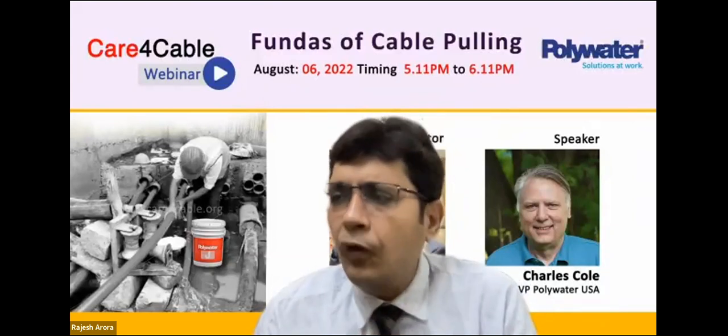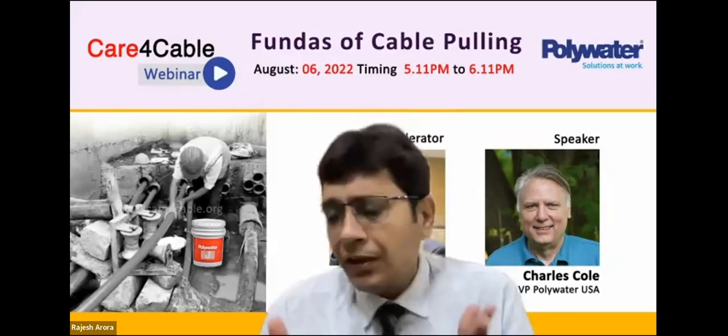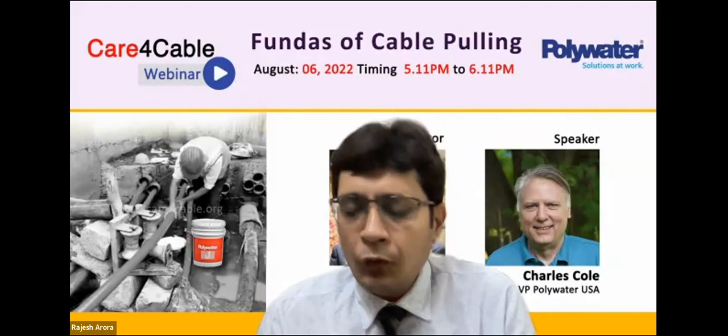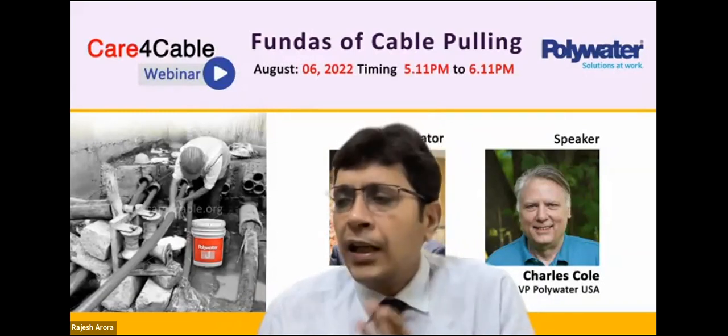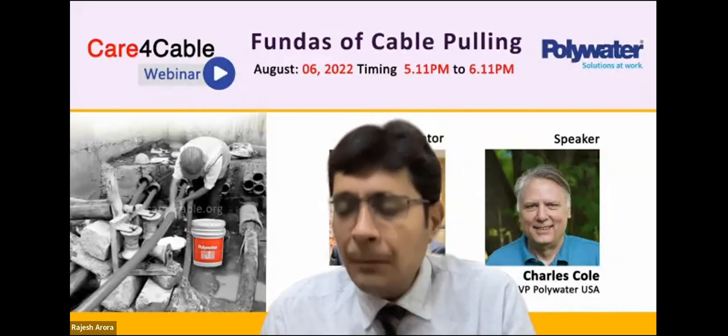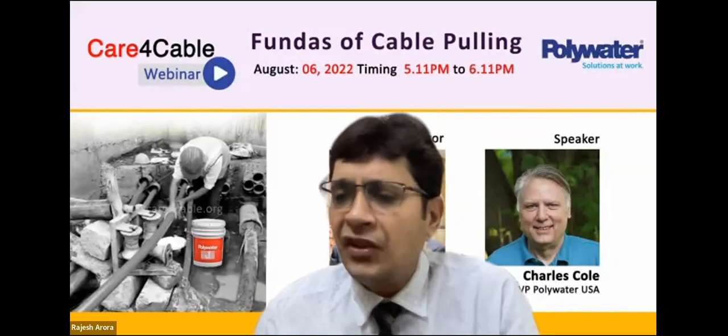There are some mechanical forces: tensions, sidewall bearing pressures. We have to do starting and stopping of cable pulling. We have to take care of total curvatures, low radius bends. We have to keep in mind the change in the elevations.